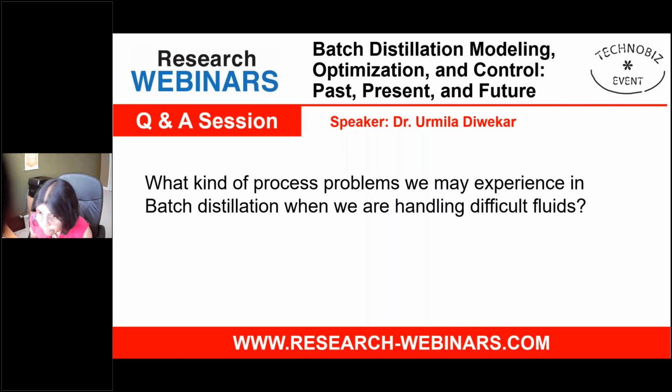What kind of process problems we may experience when we are handling difficult fluids? Difficult fluids, in the sense that if you have azeotropic systems, that becomes a difficult system. So one of the things is that you have to choose the configuration as well as the separating agent, like solvents, extractive solvents, very properly. Otherwise you may get into difficulty that even if you have a large column, large reflux and so on, you may not get the purity you want.